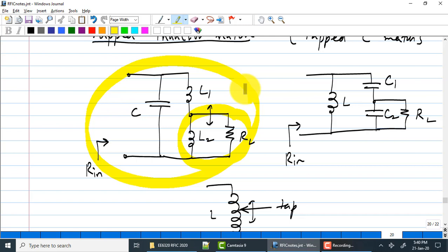For example, let us say you are trying to build a power amplifier. Remember, there are two specific cases where I said you will use matching networks: at the edge of the transceiver chip, normally the input of the receiver and the output of the transmitter. The output of the transmitter is a high power, high swing node. You do not want to use active matching elements there, because they will not be linear at all. So you will end up using passive elements.